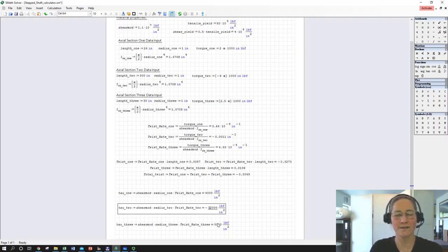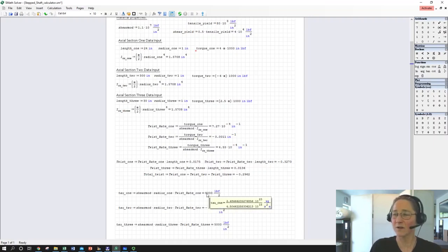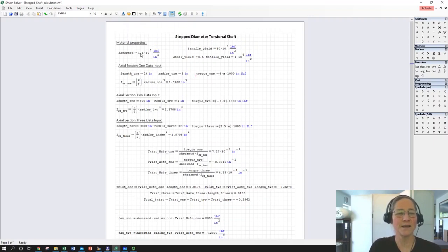But now this one is one to watch. So I have 1.2 times 10 to the fourth. It's going in the other direction, but in terms of yield, it doesn't really matter. But basically, if this got up to 20, I would be in trouble. But I could look at adjusting my torques. I could look at what happens when I go up. We're not seeing as much of a change here. That's reacting, of course, in our first section. But basically, we can continue to make changes as we need.